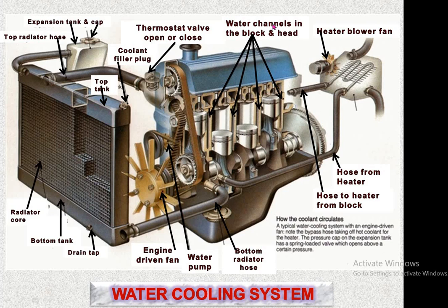These are the water channels inside the engine block as well as on the head of the cylinder. Then the thermostat valve opens or closes. This is the thermostat valve. According to the temperature set, it opens or closes, and it passes the hot water from the top of the cylinder head to the upper tank of the radiator.